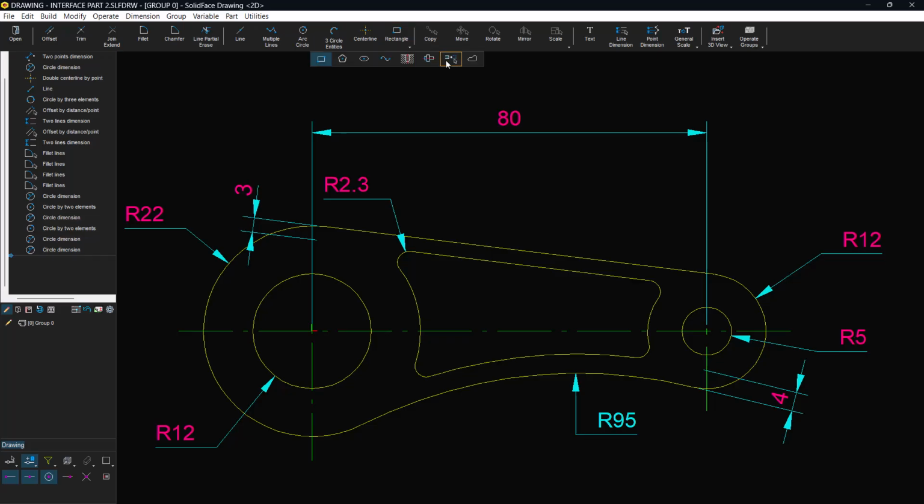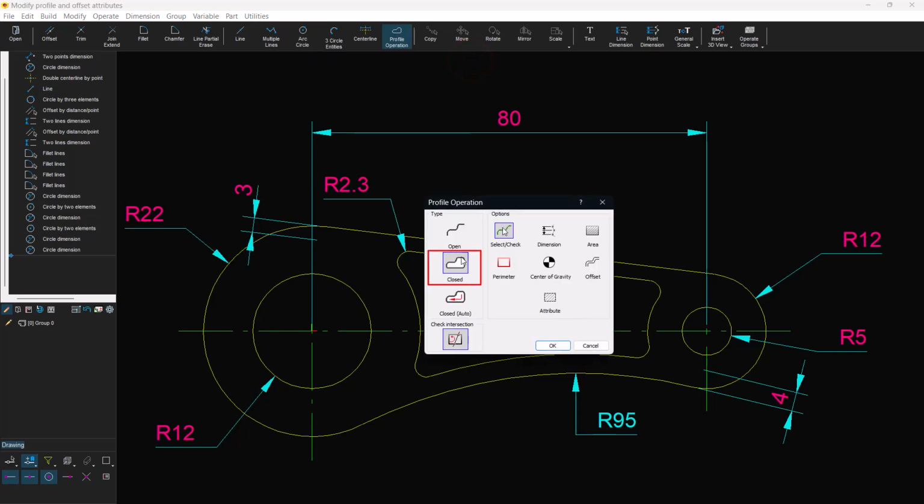Activating the contour function. This option is part of Geometry's submenu block. In the closed contour, when there are vertices with more than one line, the user must identify which line to continue the contour. With the Auto-Close Contour option, you identify the line inside the contour and the function searches for the contour automatically. The Check Intersection option looks for lines that intersect the contour, not just at lines' endpoints. In our case, the contour lines are connected at the endpoints. Do not select this option.